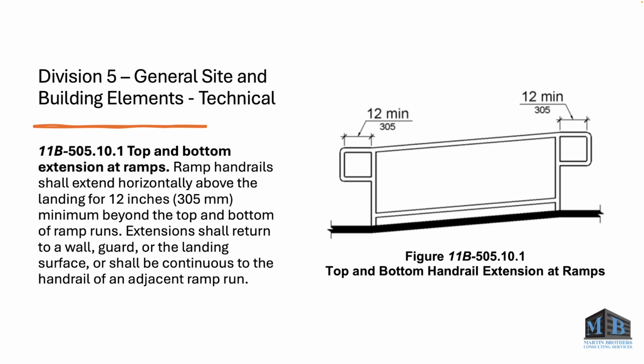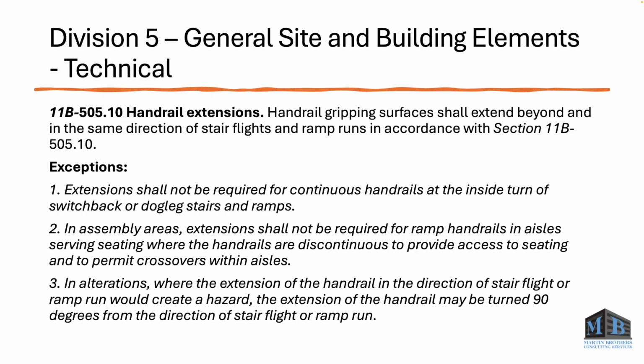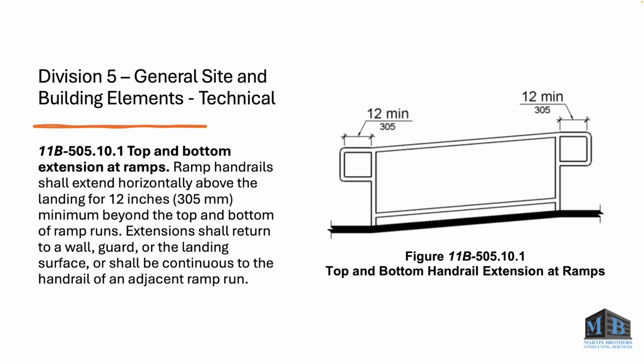And you can see in this figure that P shape that I was talking about, the bottom of that P, as long as that's at 27 inches or lower, it's cane detectable and it's not really a projection hazard. So you could try to leverage that exception in the previous slide, 505.10, exception 3, but if the argument could be made that all you have to do is simply weld that little bit of pipe underneath your extension and it's no longer a hazard, you should probably do that.